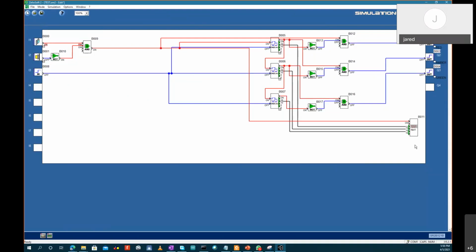Now you can start, you can reset. Okay. And release. And start again. So you've seen the reset is working, start is working. The emergency stop should be able to reset. It only resets the values, but you need to have one that is able to stop every light. So this one is just to reset the counters. This one is the one that is able to stop every process. Okay, so that's why you see it begins with the start signal.